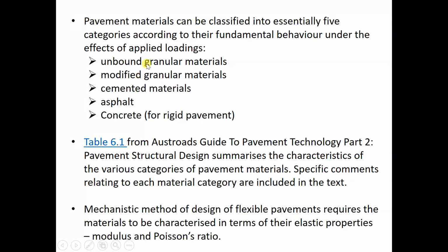Another thing, I think the subgrade is under the category of unbound granular material as well. The soil is unbound granular material, unless you modify the subgrade, or even strengthen it and stabilize it, that means stabilize it with cement or whatever.